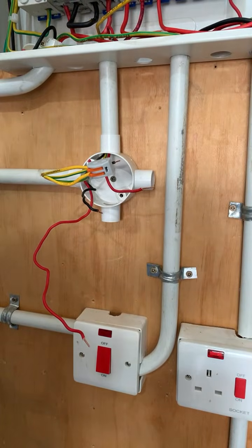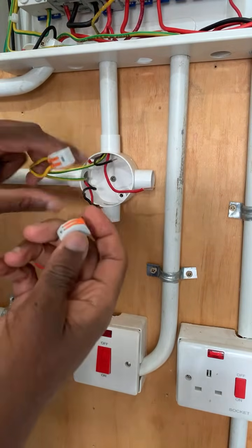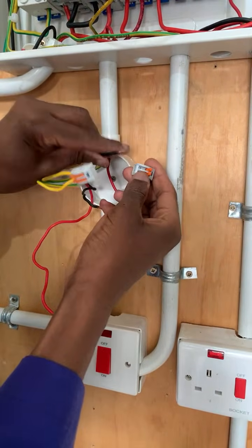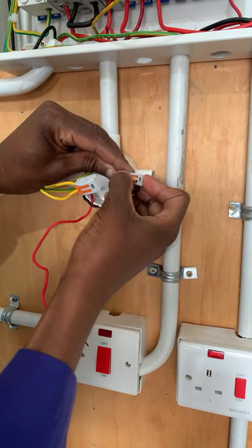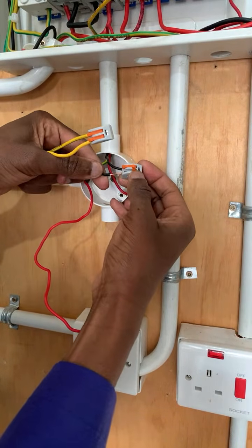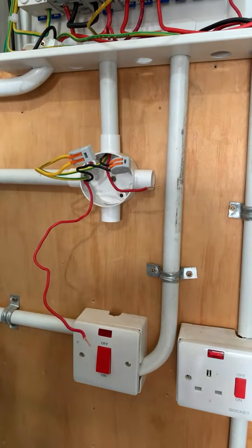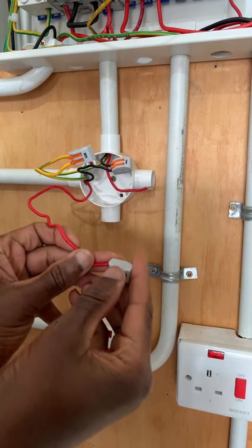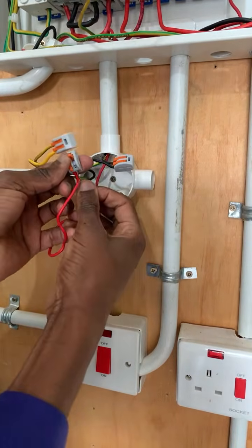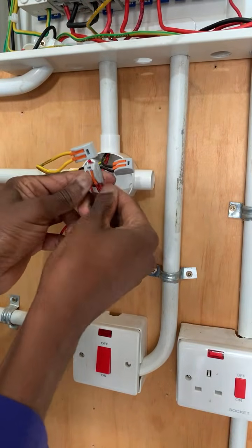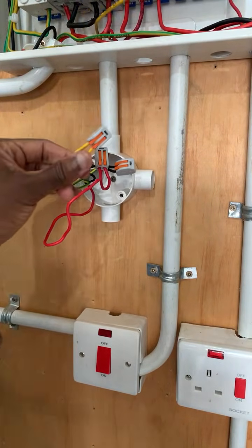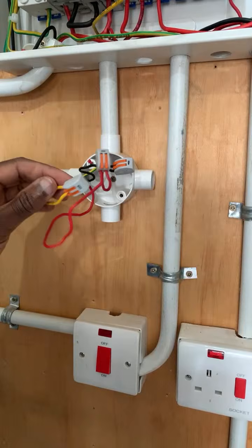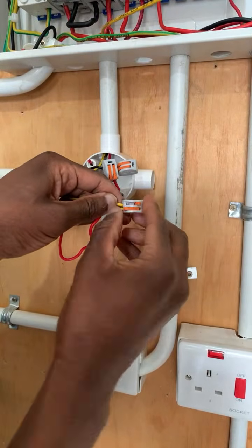Very fast, no? And it goes to the neutral. We'll do the same. I'll take another WAGO connector, lift the levers, then insert the neutral, first neutral, second neutral, clip like so. Remaining with the line, insert it here, clip, then this one, clip. Look at that, very neat. The next time that I want to do repair work or get rid of them, it will also be simple. Let me demonstrate using that.